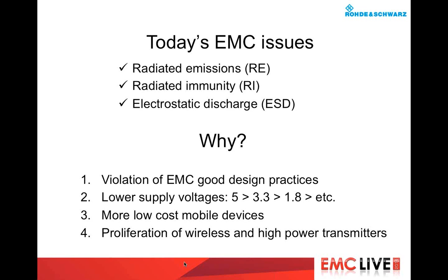But I think also the issue is digital circuits are being powered by lower and lower supply voltages. We started out with 5-volt logic, and then 3.3 and 1.8, and now even 1.2 or lower. And as the supply voltage drops like that, the noise margin also drops. And so it doesn't take much of an energy source to disrupt digital circuitry.